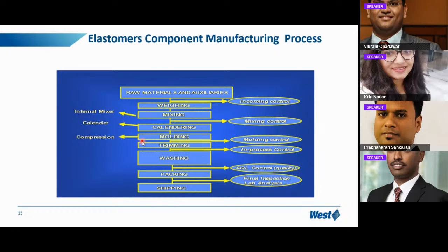So whatever size you want, you can just mold that, and you can form the size, whether you want serum stoppers or whether you want a Lyo stopper. So that mold should be applied, and then finally a trimming. So there is a big sheet. You need a small stopper, so there is a trimming of each stopper, and then finally washing, and then packing and shipping. So this is the standard process of preparing elastomeric stoppers.